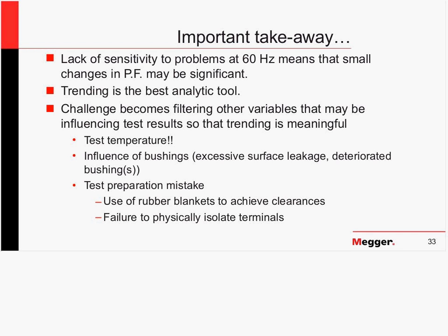Also, because of this lack of sensitivity, trending is going to be your best analytic tool, so that you can ask, have I experienced any change? But if you're going to rely on change in power factor to detect a problem, and take small changes seriously anyway, then the biggest challenge you're going to face is that you have to filter out other variables that could be influencing your test results so that trending is meaningful.